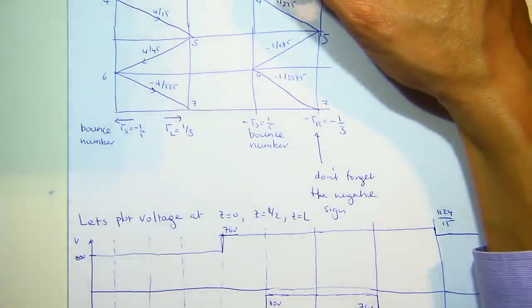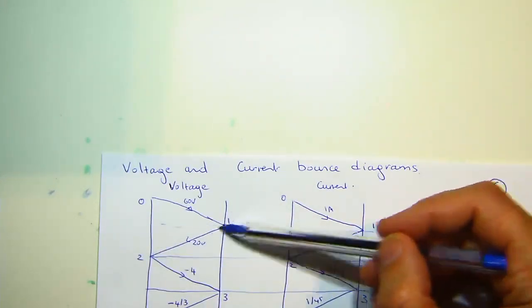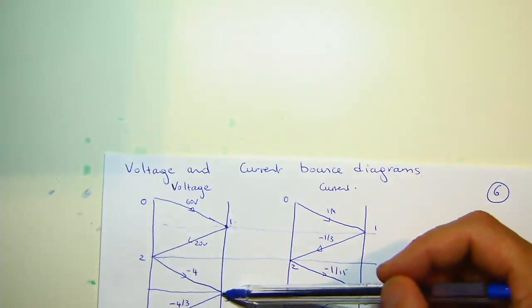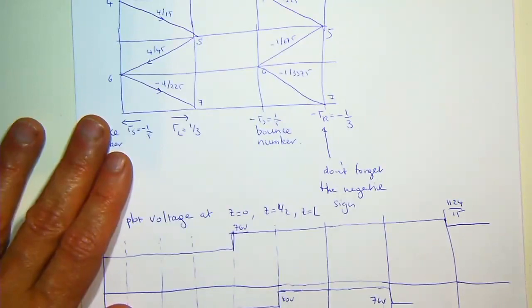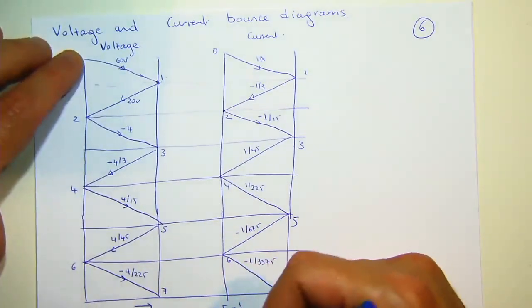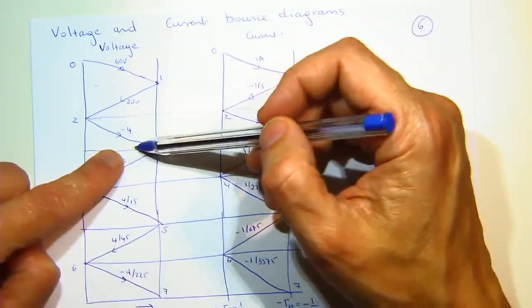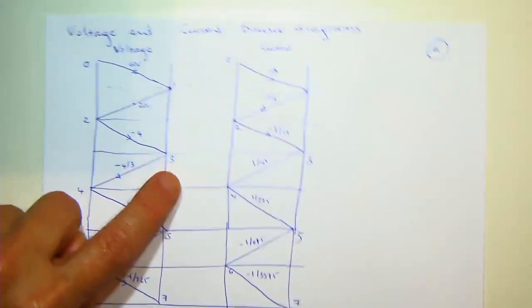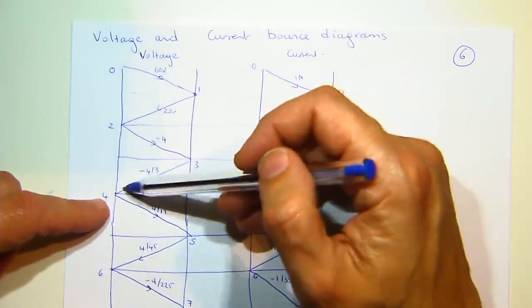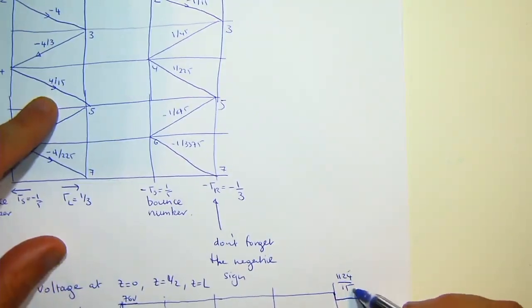And until we get the reflection from the load back to the source, and it hits us at the load, that voltage is going to remain at 80 volts until we get that reflection, which makes the voltage go down a little bit, right? And likewise, when you're at the source, remember, you get the -4 volts occurring here, so it goes from 80, -4 is 76. And then you have another reflection, you've got the -4/3 plus the 4/15. So therefore your resulting voltage is 1124/15.